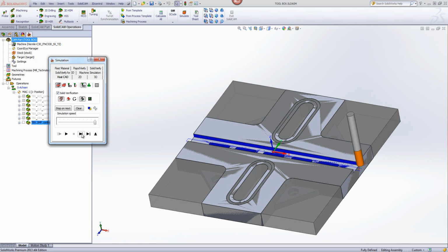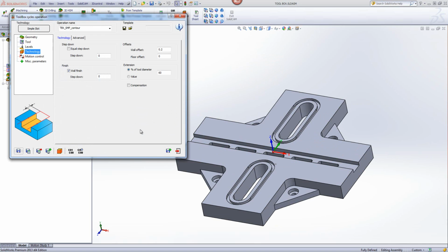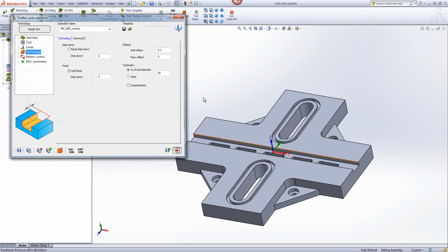Our first step, our now second finish step. That's all we had to do. And it's a very simple operation, but it makes the programming time of this slot easy. I did not have to make 2 chains in opposite directions and have it go up in this end and come back in the other side. No lead in, no lead out necessary in this particular case. That's all I had to do. All right, that's one simple case.